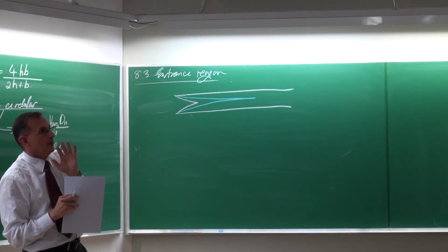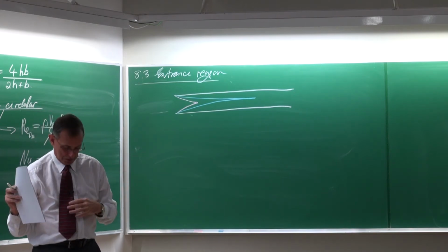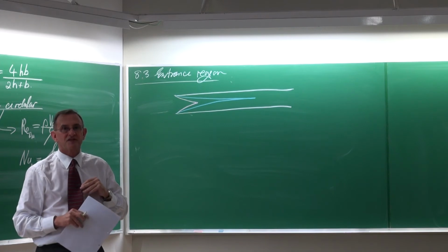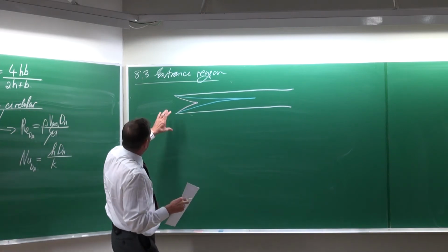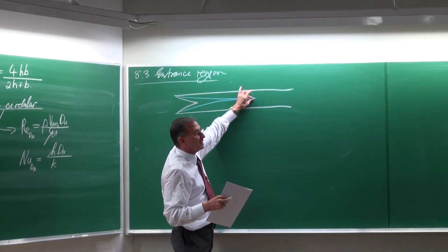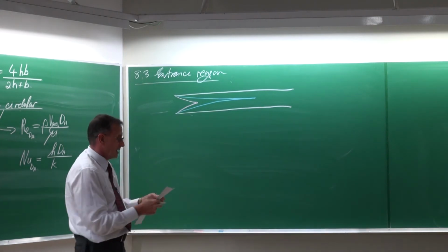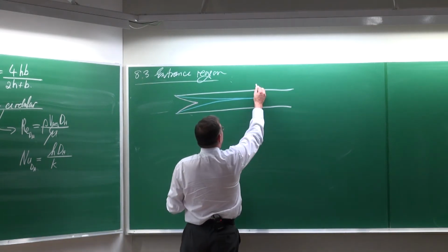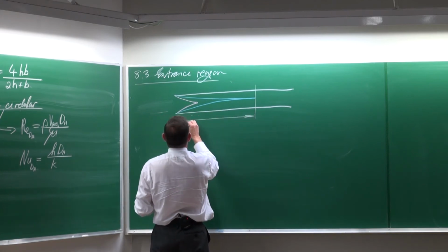And one of the first things that I've explained when we started with this lecture is that with internal forced convection, there are many cases where the two boundary layers meet each other. And that is going to be very, very important, because that distance we call LH.